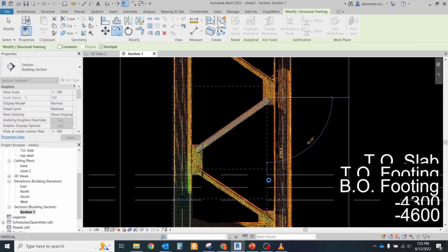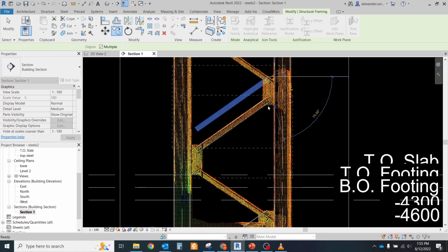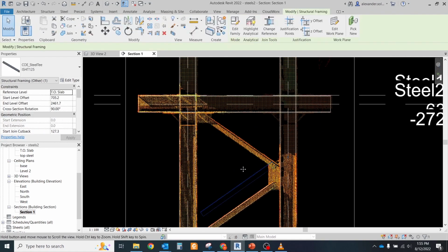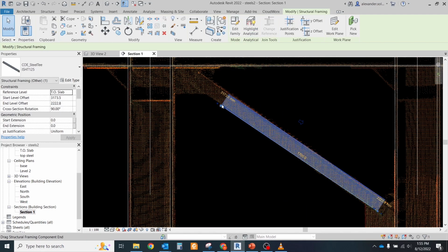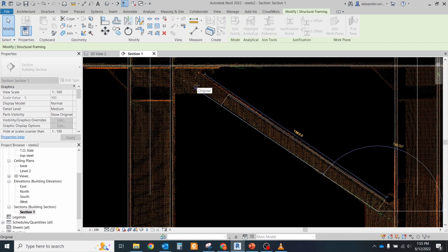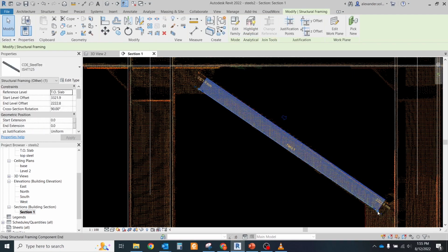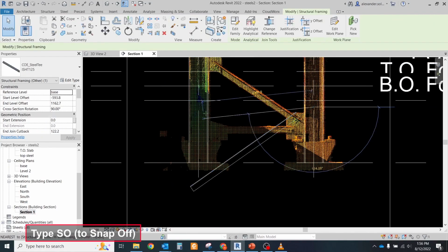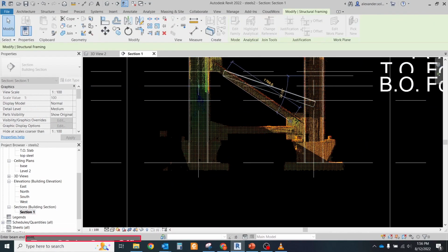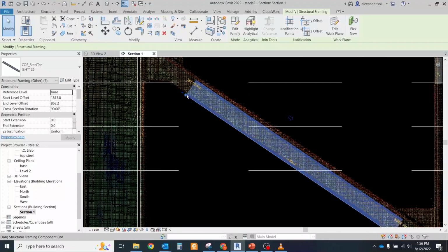When you define all your main steels, you can just copy and paste them and align them to the point cloud manually. Sometimes it's faster than trying to fit each element into the cloud. Use different clipping tools for separate point clouds and use different views to align the steels. Floor and ceiling plans are used to align the horizontal position of the beams. Elevation and section views are used to align the vertical position of the beams.